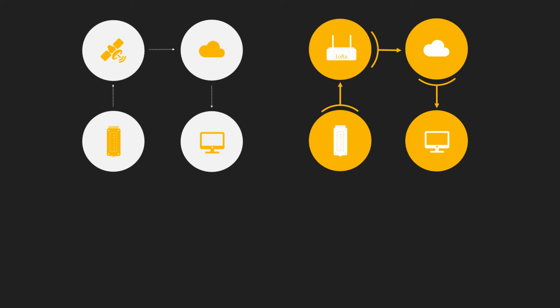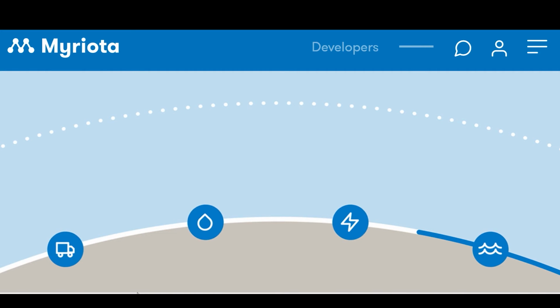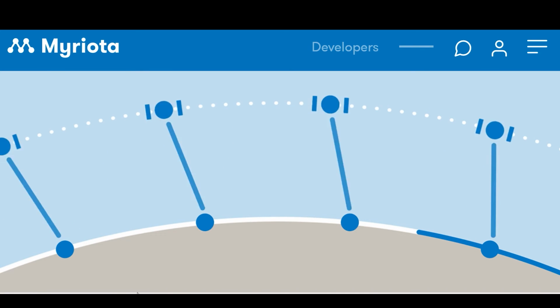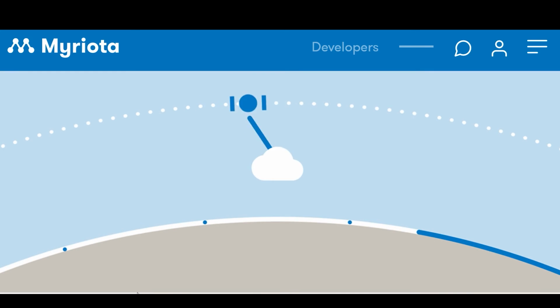All of these devices employ either LoRaWAN or Myriota satellite for comms. Both of these options are extremely power efficient and much cheaper than more traditional communication methods such as 3G or Iridium satellite. Myriota satellite technology is perfectly suited to CP monitoring and allows transmission from anywhere in Australia without the need for installation of any other infrastructure.